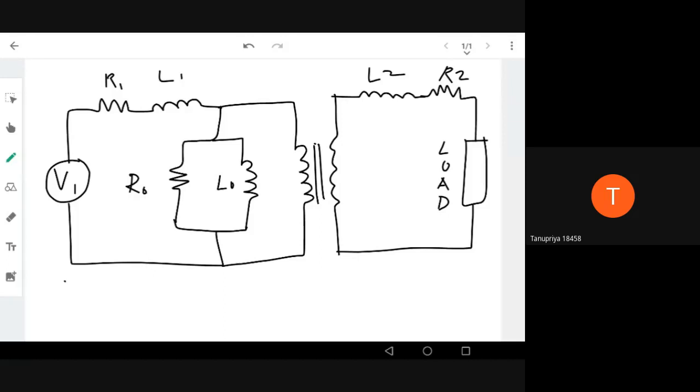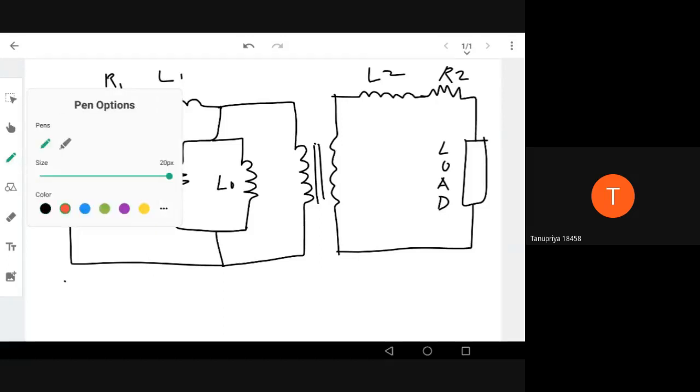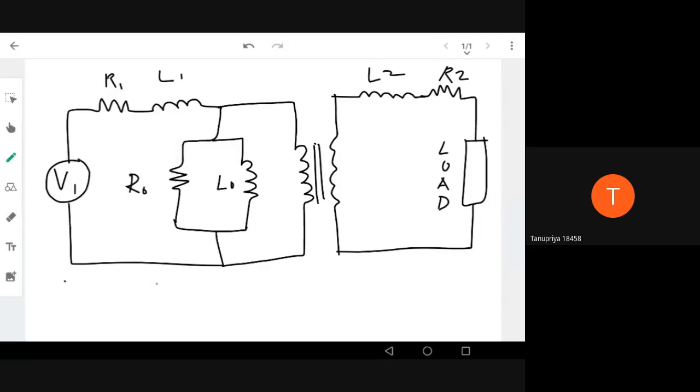Here, this is the primary voltage V1, this is the secondary voltage V2, whatever. So what we have done is we are trying to model the transformer using resistances, inductors, etc., based on the short circuit test and open circuit test, which give me these values of R0, R1 and R2 and L0, L1 and L2, etc. Right? So now how to analyze this? We have different circuit analysis concepts that can be applied here. We can use the Kirchhoff voltage law.